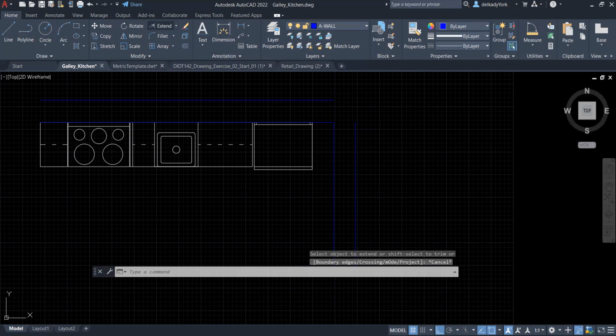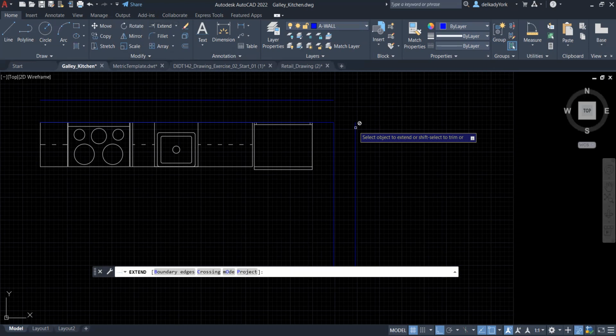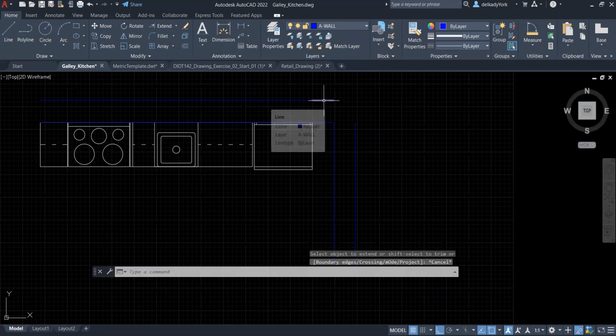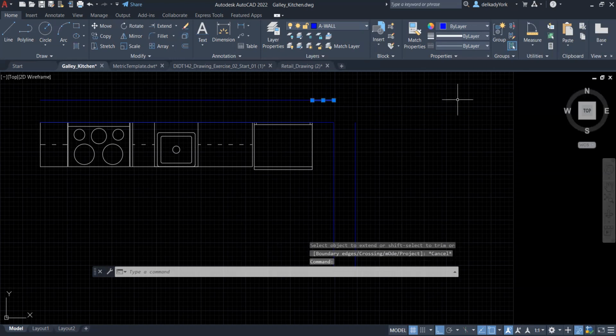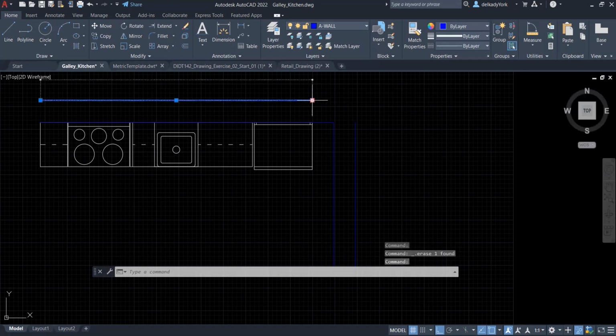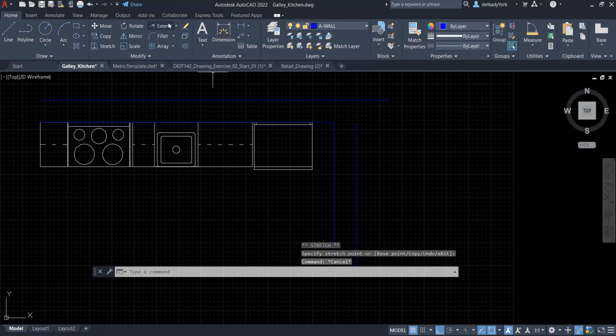When you hover and it's not picking the line, maybe you can hover here. When this happens, you know that it's not really working. The boundary edges are not really clear for AutoCAD. So the best thing is I'm going to delete that line, and then I'm going to click here, and I'm going to extend this a little bit like that. And then I'm going to go to extend, and I'm going to do this. All right. Again, clicking here and trimming the excess part.